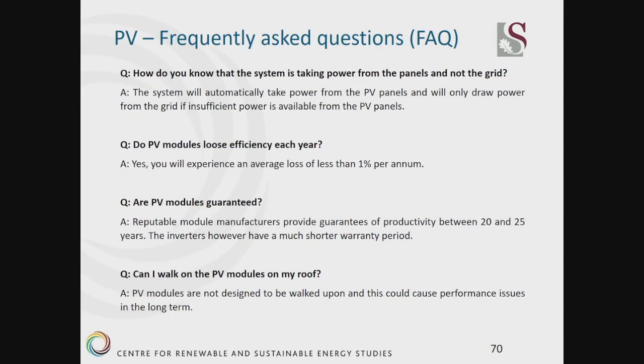Can I walk on PV modules on my roof? This is a typical question, and although PV modules are quite strong and will take the loading, and won't break immediately, PV modules are not designed to be walked upon. And this could cause performance issues in the long term, with micro cracks being created in the panel, and these develop further as time goes on.